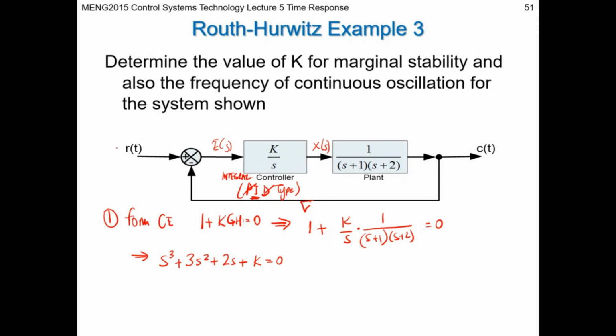So instead of the voltage just simply being the error between the output and the input, now the voltage going into the plant, or the actuating signal, whatever it is, could be voltage, pressure, flow rate, any of those kind of things, would be what's produced as a result of the error being multiplied by the controller action, which is k upon s.